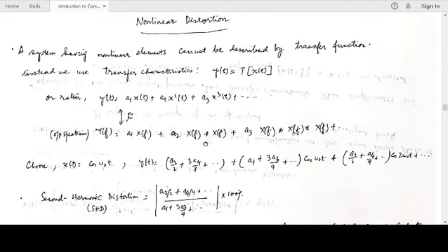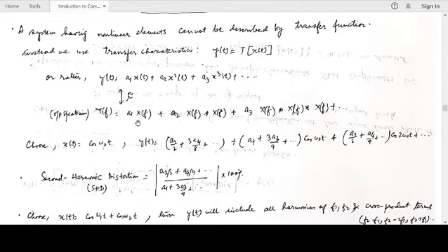Okay. So what do we understand from here? If, for example, the signal x(t) and its Fourier transform X(f) is band limited over a band, X(f) convolved with X(f) spreads it to twice that frequency band. The three convolutions spread it to 3 times or more. So that means the output spectrum is no more band limited. Even though the input signal is band limited, the output spectrum spreads over wide frequency bands. This is the first important distinction from linear distortion. In the case of linear distortion, if the input was band limited, the output was limited to the same band.